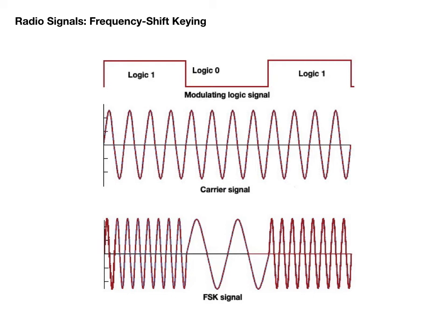You can calculate the approximate bandwidth of an FSK signal by doubling the baud rate, then adding the frequency shift. For a 45.45 baud radio teletype signal with a 170 Hz shift, the approximate bandwidth would then be 2 times 45.45 plus 170, or 261 Hz.